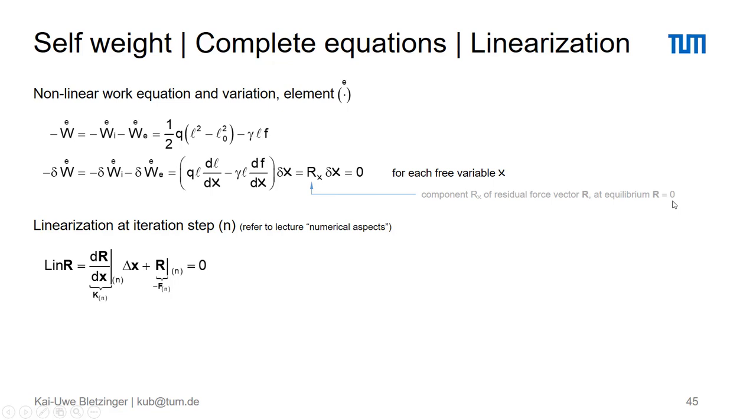We have seen it already in the iteration history for the application of stiff. And that exactly is the basis of nonlinear analysis, that we take the residual force vector, that means in particular all components of that, which each of them are nonlinear functions in terms of the variables, and try to solve iteratively for each of these components of this vector to be 0. And we do that by applying the Taylor series expansion. That's exactly the Newton-Raphson technique.